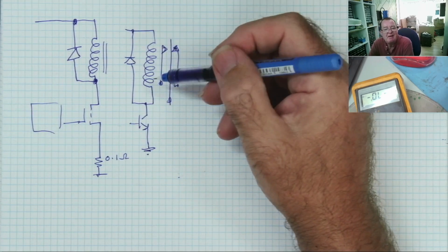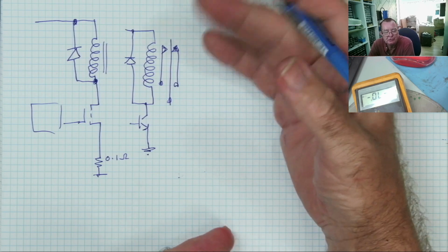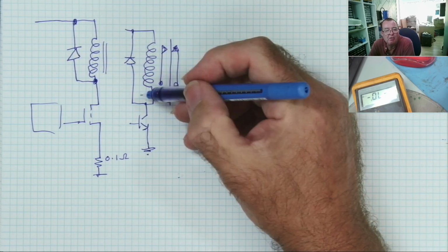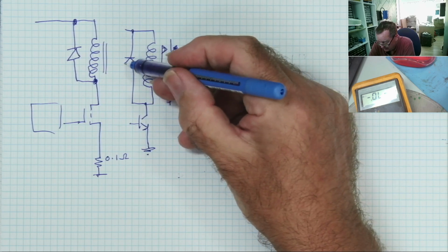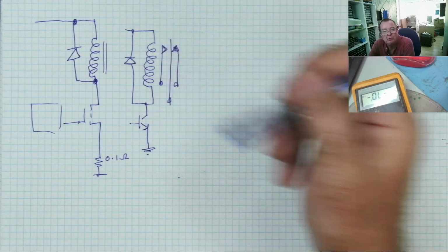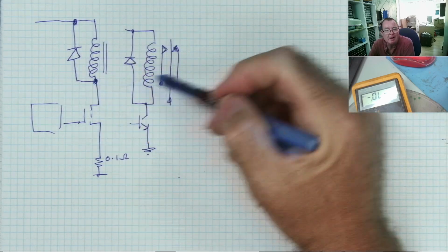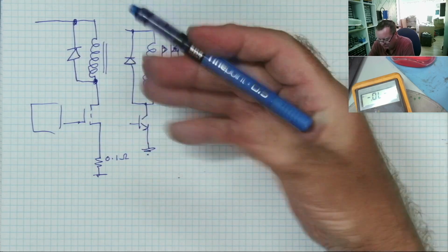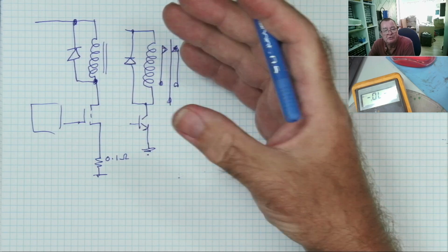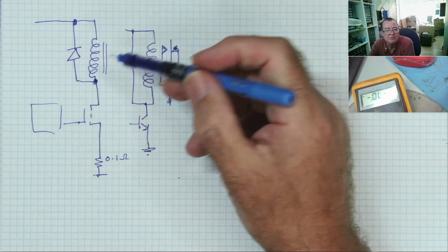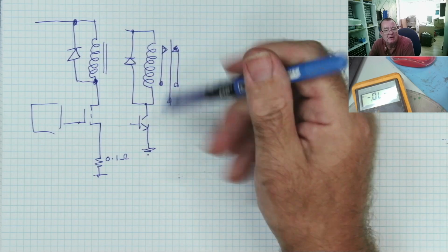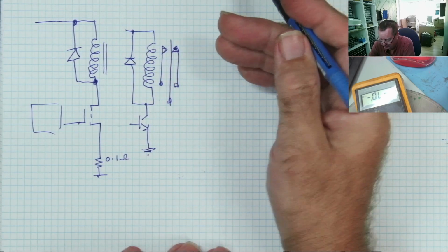Now because the relay coil has some resistance, usually 100 ohms or something like that, could be less, this may not look like a short across the diode, but it'll look like it's conducting in both directions. It's not, it's the coil. You can prove it by lifting one end and you'll test the diode, or take it out altogether and test the diode and find it's fine. So where you see inductor coils with diodes near to them, they can look like they're short when they're not, even though there's no fault condition.